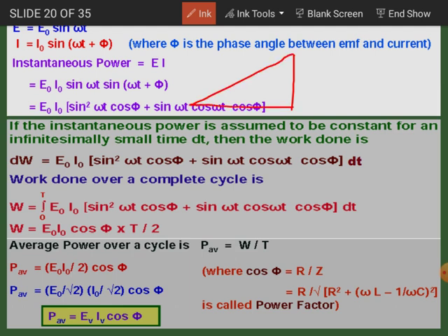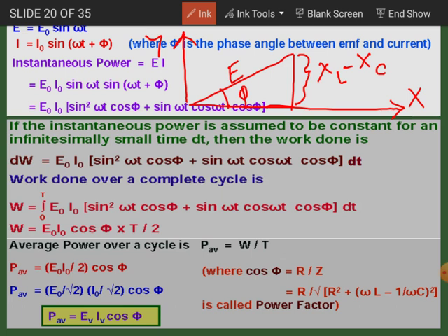If we redraw it like this, the y-axis is here, the x-axis is along this side, like this. This angle is phi. This is equal to E. So we take this as XL minus XC, and this part as R. So instead of VL, that means in terms of potential drop, if we replace it by the resistance, then this triangle we call the impedance triangle.